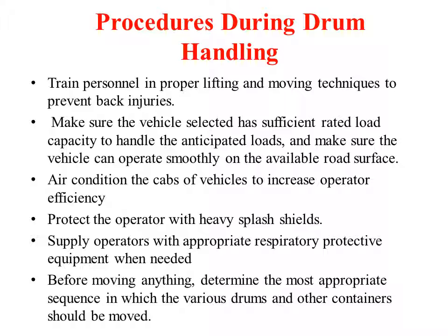Next point, stir corrosives slowly and carefully in cold water when the job requires mixing corrosives and water. Sometimes corrosives have to be mixed with water, and this mixing is usually done with cold water. When mixing water with corrosive, the water is slowly poured and then mixing is done. If the water is poured fully or suddenly, there is a chance the chemicals will start boiling, resulting in vapors, fumes, or even spillage. So this has to be avoided.